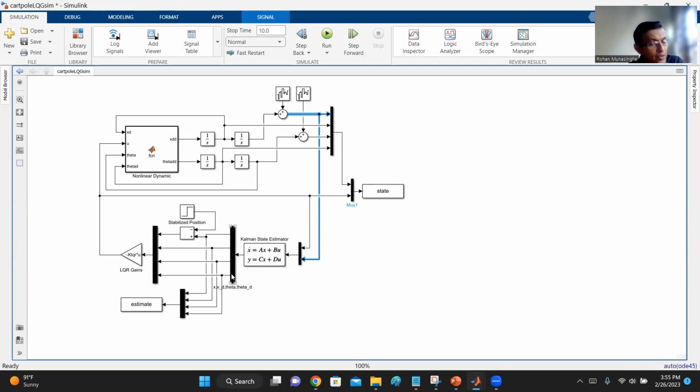Now see how beautiful this is, right? And then we have no problems with the feedback controller, LQR. So let's give it a try and see. If this works, we get rid of 3 sensors altogether. We only need one sensor.